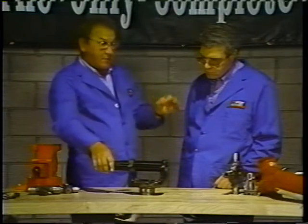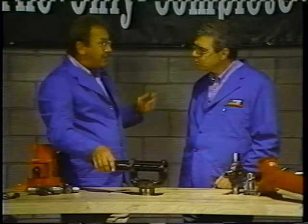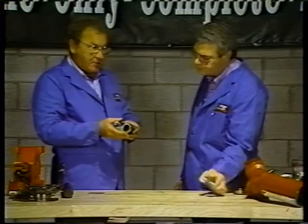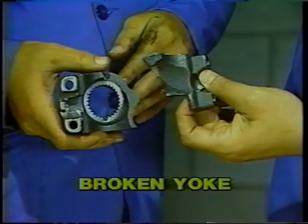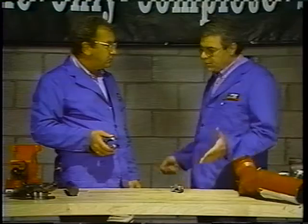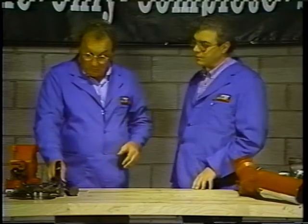Now, the wear and alignment of the yoke cross hole are very critical problems because they can lead to complete driveline failure. What would cause the ears on this yoke to break? This happens when a U-joint breaks as a result of shock loading. That ends up destroying many of the attaching parts, like this yoke as well. Well, if that's all we have for yoke failures, Tom, let's go on to the drive shaft tubing.